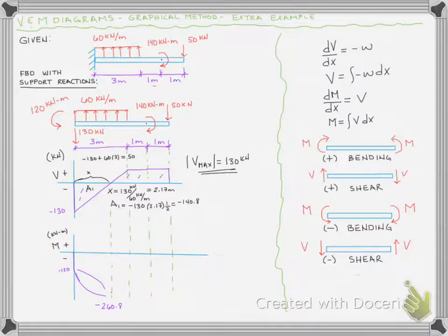So if we look back at our shear, we can see that the magnitude of the shear that we're adding gets less and less every meter that we go over. And since the slope of the moment diagram is equal to the shear, if the magnitude of the shear is decreasing, then our slope should be decreasing. And so we can draw this with a decreasing slope. And again, if it helps you to imagine decreasing, don't forget that you can draw your little person hiking down the hill, and so the slope would be getting easier and easier as they approach the 260.